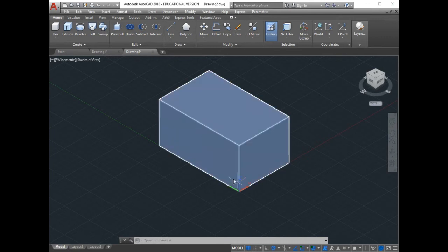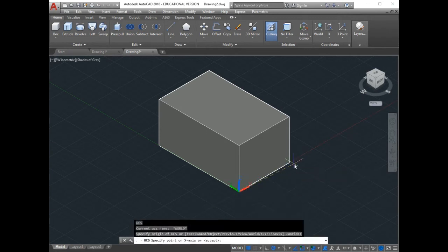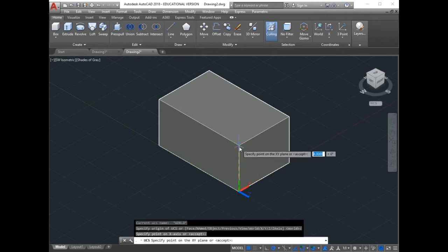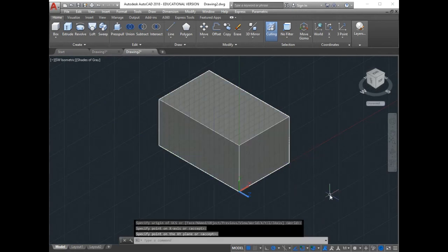Clear, guys? Now I'm gonna repeat the step of the user coordinate system again. Guys, you just simply write down UCS, and then you push enter, and then you pick up that corner, you pick up a point along that line if you decide to make your x-axis in that direction, and then you pick up any point along that vertical to put your XY coordinate system. And now it's time to go and put your dimension.